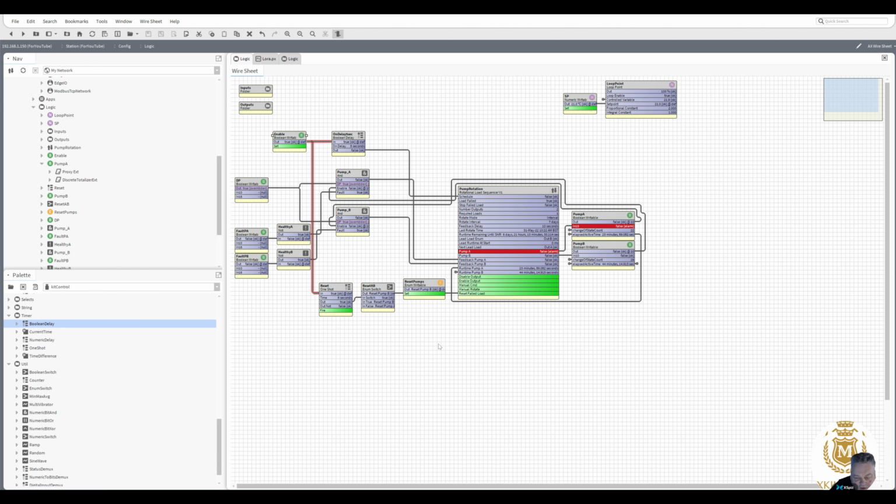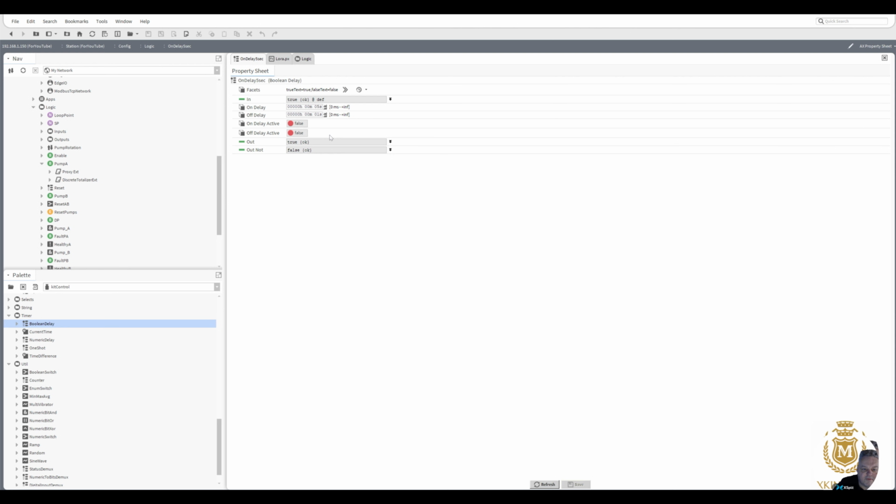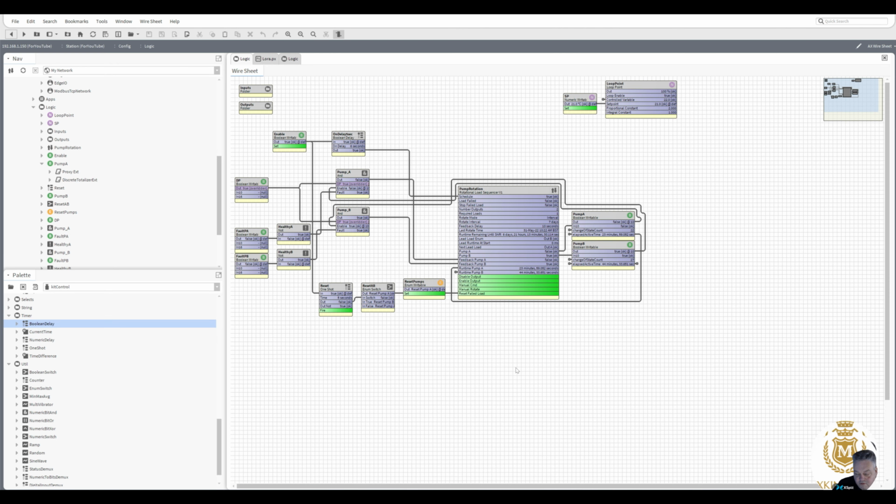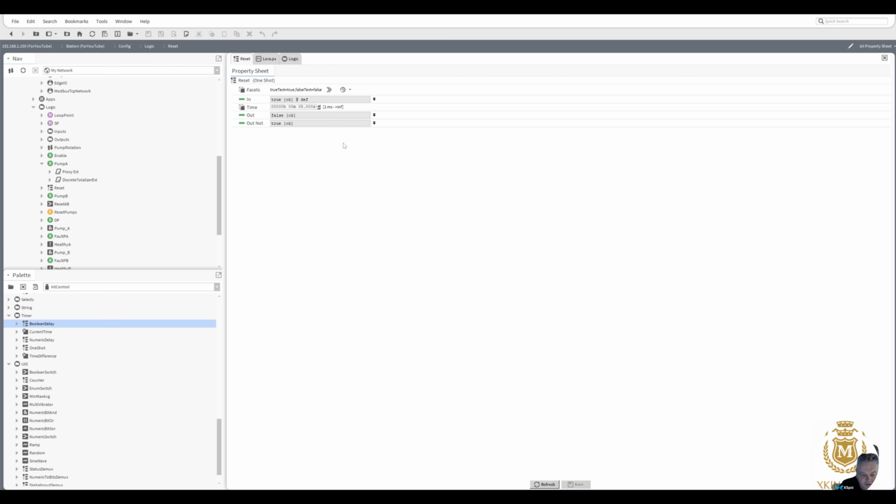We've got the DP on. We've done the reset. We've enabled the scheduler. Like I said, that wants to be about 6 seconds, because if we fire at 5 seconds. No faults. Pump B's running. Pump A isn't. Now I would have expected to see pump A run, so it could have been this 5 seconds here. In fact, I'll turn that down from 5 seconds to something like 3 seconds.